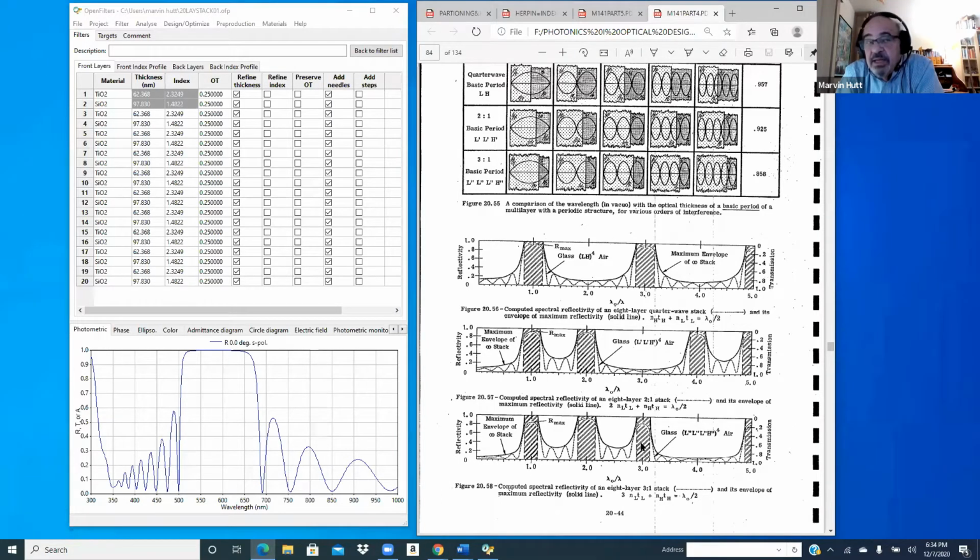When I design semiconductors, I want to laser write the pattern of the etching for the design. Now I want those things to be very, very tight, so I want the wavelength to be in the UV. So I have here a high power laser, which will produce a lot of ultraviolet for me to burn and write those fine structures and make very fine structures for semiconductors.